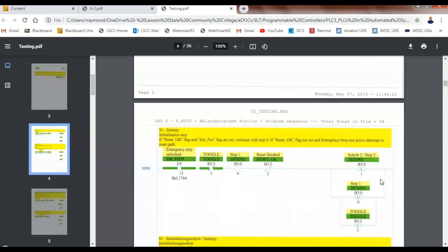In big diagrams, 90% of the relays are in there just to make decisions. And that's what a PLC replaces. It replaces all the decisions. But we do it with internal relays. So I think I showed y'all a picture of a relay cabinet, and then they put a PLC in it. Now, of course, I need to show y'all Lee's out there at the cement plant. Yeah, like I said.